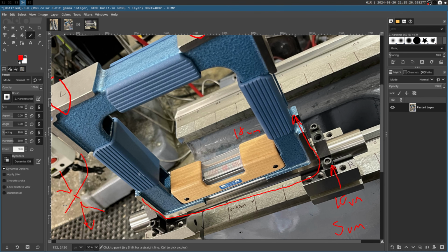That's a perceivable amount. That's enough to trip on. That's enough to stub your toe, right? Your concrete, your foundation, your house, the dirt is moving way more than 10 micron, right? It's reasonable that you could have an inch of move on a crazy winter. Now, obviously, that's normally going to be shear in specific areas, but it is completely reasonable that this will move enough that I couldn't go out here, take one set of readings, then go out there in a week and take the same set of readings, because everything will shift.